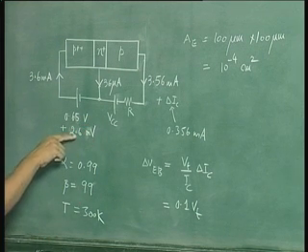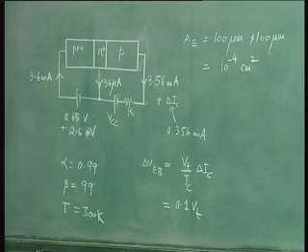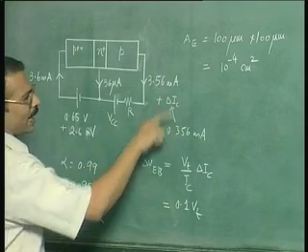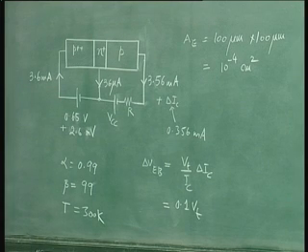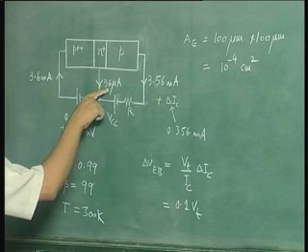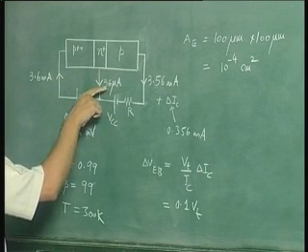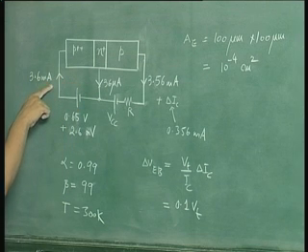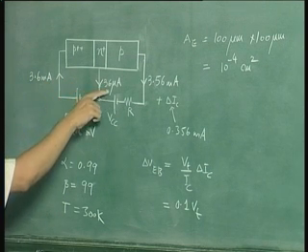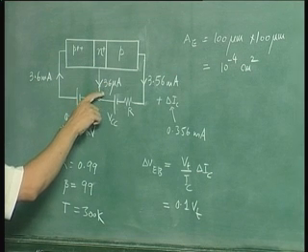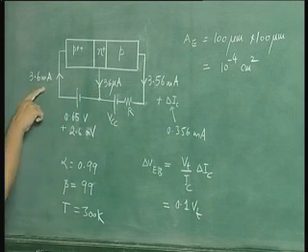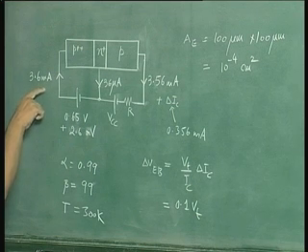So 2.6 millivolts increment over 0.65 volts will produce an increment of 0.356 milliamperes in the collector lead, and obviously this will also produce an increment in the base current as well as the emitter current. So these increments will also be 1/10 of the corresponding currents. So this will be 3.6 microamps increment in the base current, and it will be 0.36 milliamperes increment in the emitter current.